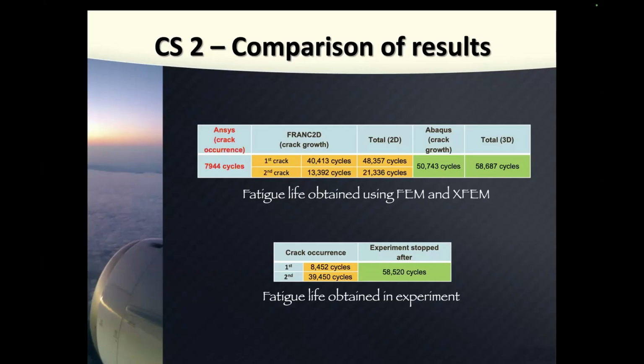If you want to apply any of these laws to predict the number of cycles, you have two options from my point of view: to use NASGRO, which is really reliable because they did hundreds of experiments, or to carry out your own experiment, take a sample from your material, do an experiment with a specimen, and find the coefficients.